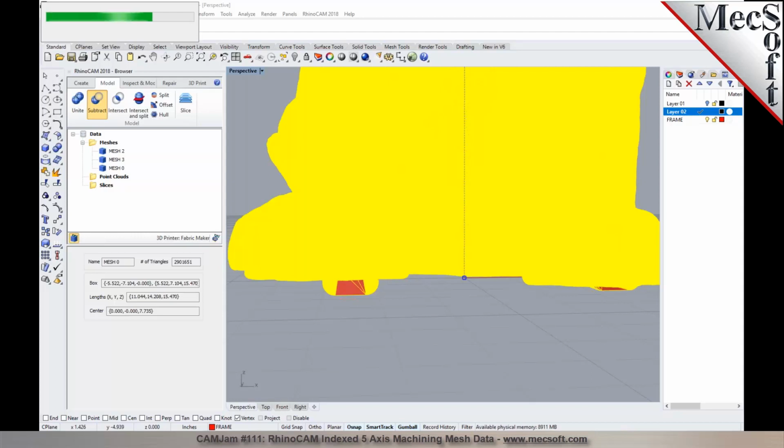So if you want the frame also to be a solid tube, the other one, you can also do the modeling in Rhino itself, or bring it in from your existing CAD system.